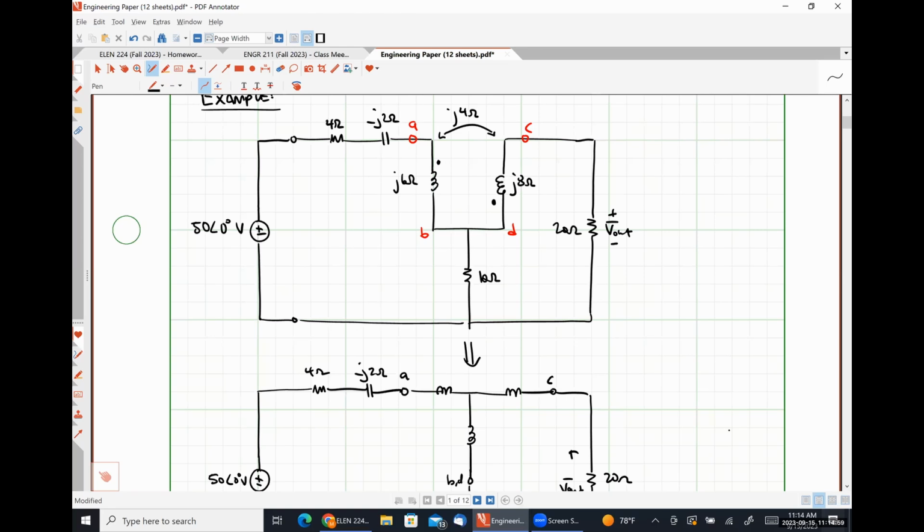So we'll have up here. This inductance right here is Ly. So that's going to be L2 plus M because the dots are on opposite sides. So 8 plus 4 is 12. And then down here is just going to go -M or -J4 ohms.